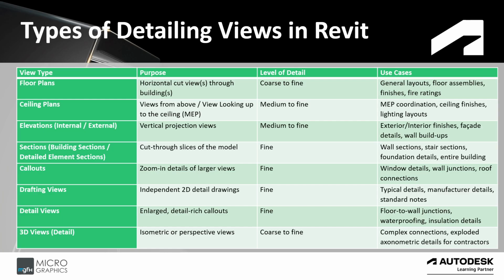You can add a color or hatch pattern to all the new walls, defining the phases by color and hatch pattern. You can quickly hatch the same walls on all views by applying a view template, not having to rehatch or recolor each view for the same element like you are required to do manually in AutoCAD, such as elevations and sections and detail views, floor plans, and more, saving a lot of time on repeated work.